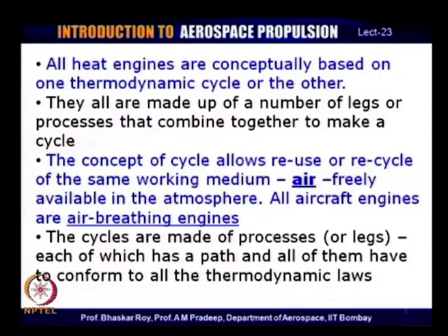Now, this is very important. The working medium we have in abundance around us is air, and that is freely available in the atmosphere to us. So, all these cycles and all these engines have been created with the purpose of using freely available air as a working medium, so that the bulk of the working medium that is used for creating work, and in our case creating finally thrust, is available in air, and as a result of which all aircraft engines are essentially air breathing engines.